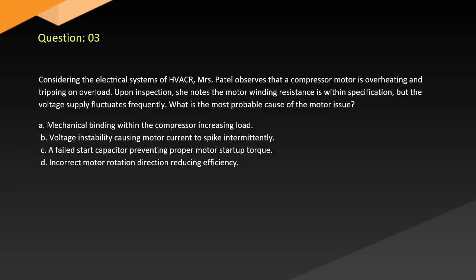Question 3. Considering the electrical systems of HVACR, Mrs. Patel observes that a compressor motor is overheating and tripping on overload. Upon inspection, she notes the motor winding resistance is within specification, but the voltage supply fluctuates frequently. What is the most probable cause of the motor issue?